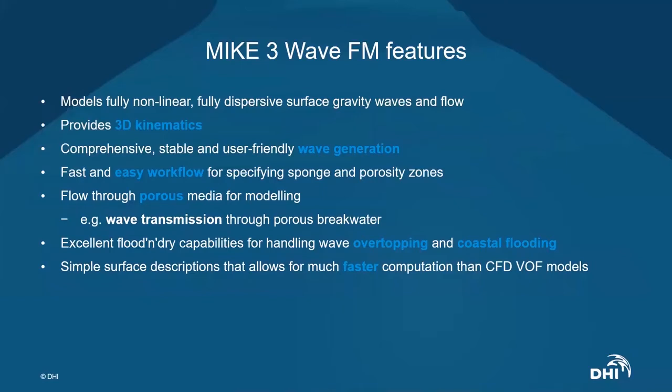When we think about the computational time of the model, this model is actually quite a bit faster than your typical CFD volume of fluid method. Compared to a general CFD volume of fluid, we are performing significantly better, because we are resolving only the necessary water regime that you are interested in, and we are not wasting computational time on empty cells above the surface elevation.